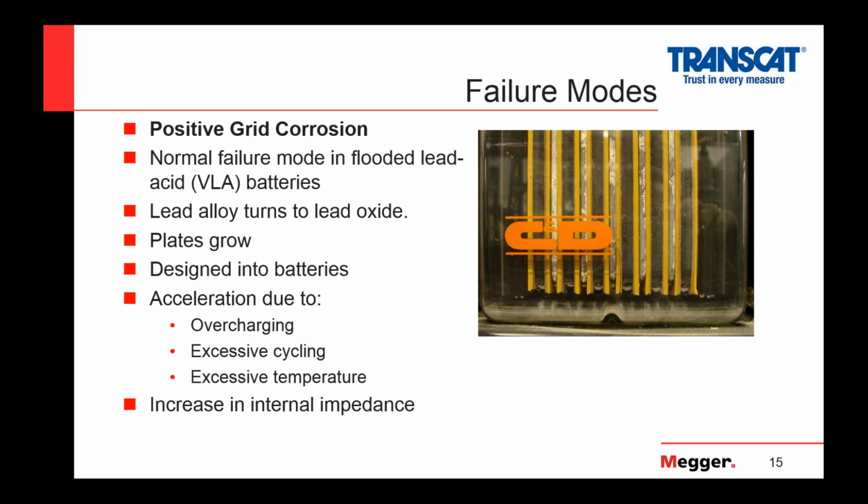What causes excessive heat? One, overcharging will cause excessive heat. Excessive cycling, excessive temperature. And as you get that, the chemical reactions will proceed faster, grids will corrode faster, and the internal impedance of the battery will rise.